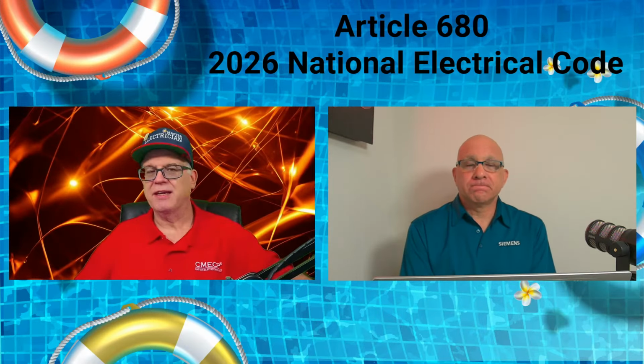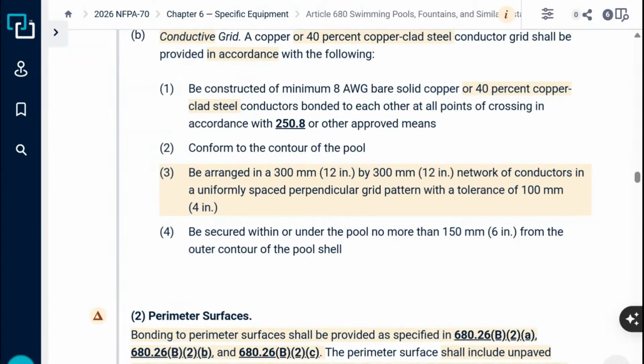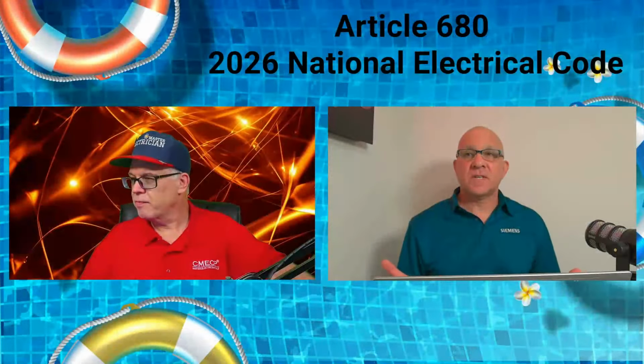Because as we see, to do this, it's got to conform to the contour of the pool, basically cover the whole pool and the contour of it. Now, they have to be arranged in 12 by 12 inch squares in a uniformly spaced perpendicular grid pattern with a tolerance of 4 inches, give or take. That may lend a tendency to think people could make one and have a little bit of tolerance. If these are manufactured in sheets or reels, you're going to roll it off, and they're going to be uniform. The manufacturer is going to make it fine. That language is letting you go up to 16 by 16 inch.